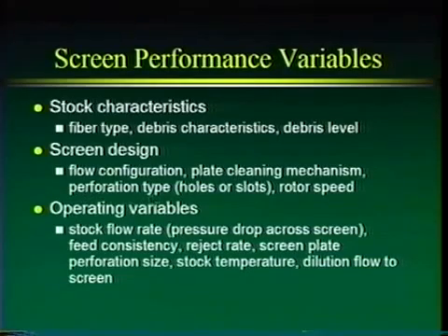And then what's the perforation type? Do we have holes or slots? What are the sizes of it? What's the rotor speed? Are the holes or slots contoured? Those kinds of things. Then operating variables. Stock flow rate. What's the pressure drop across the screen? Increased pressure drop will increase our throughput, but the increased pressure drop will increase the pressure forces that will extrude some of our softer contaminants through.